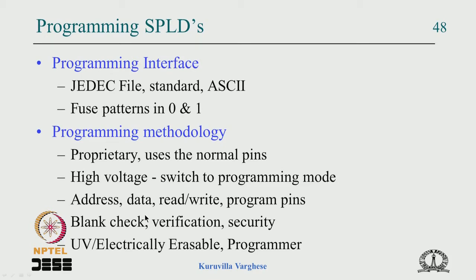There are address pins, data pins, control pins, program pins and all that. So the programmer will apply a programming pulse to the program pin, then the functions of these program pins are exposed through the user IO pins, and that is programmed. Then in the normal mode these IO pins can be used. That is how the SPLD is programmed, and that needs a separate programmer. You cannot program it within the circuit.